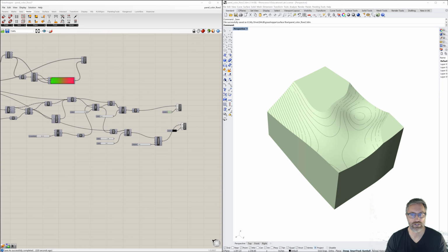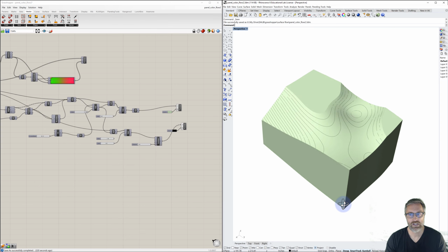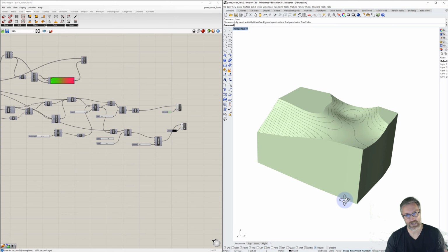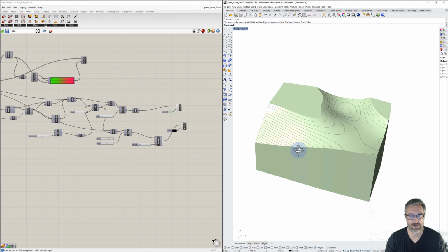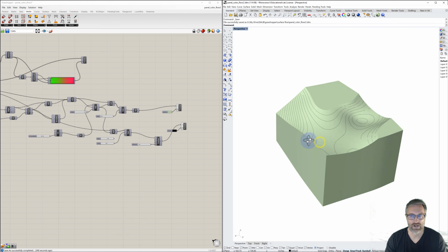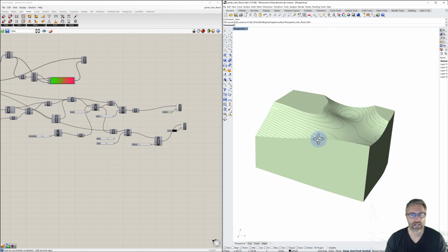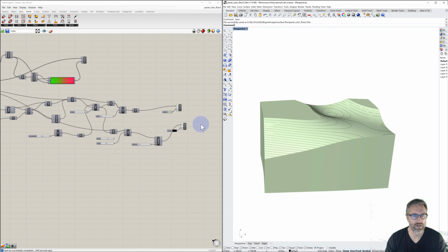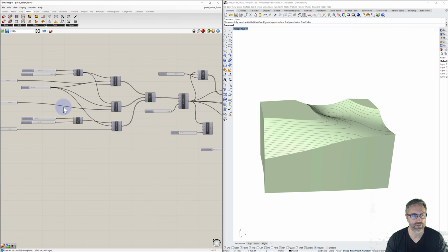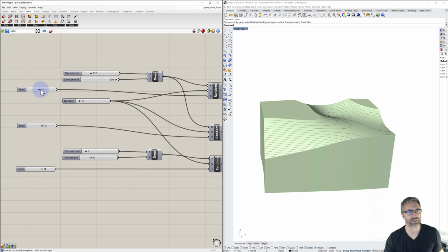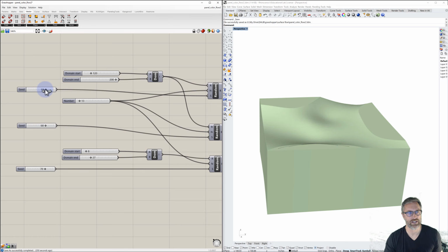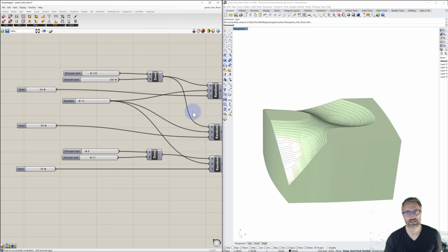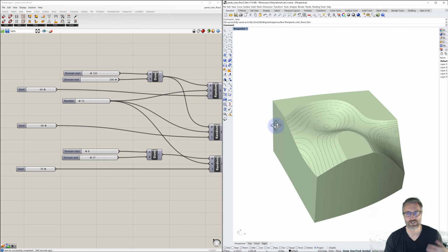So first I'll start by showing you something similar to what we'll create. What we have here is just a topography, a kind of base cut out of a thicker chunk of material. We can see a topography and contour lines, and so all of these are generated within here, within Grasshopper. And we'll see what's possible with that. I guess with the random numbers, I can also just show, there'll be a few things that might be a little funky as I do this, but we can see as I change the slider, which is just changing the random numbers, it's generating new topography.